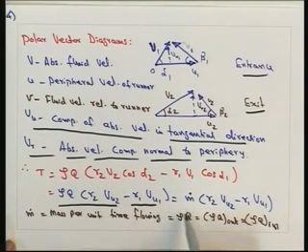If we define m dot as the mass per unit time flowing, equal to rho Q, then rho Q out equals rho Q in, since for the control volume, whatever flow goes in comes out of the system.